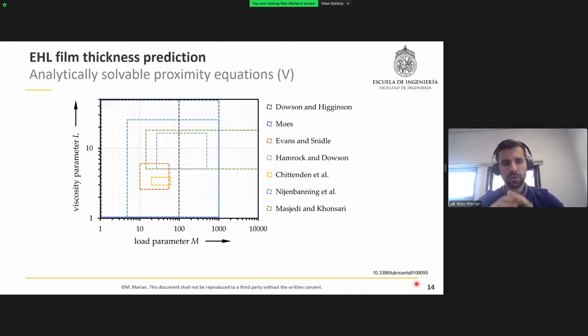And there's also quite a good agreement when we use these equations for the central film thickness outside of the stated ranges. But it's extremely important for the minimum film thickness that we only apply the equations inside the stated ranges, which basically was the base for building these equations, because outside of these domains, the equations are greatly influenced and cannot predict very well.